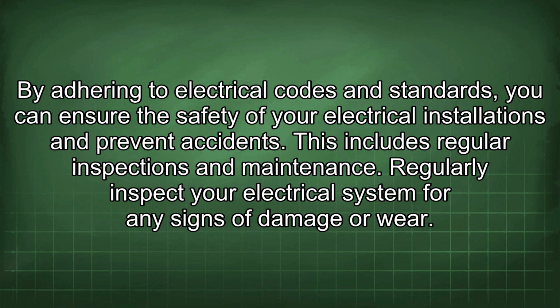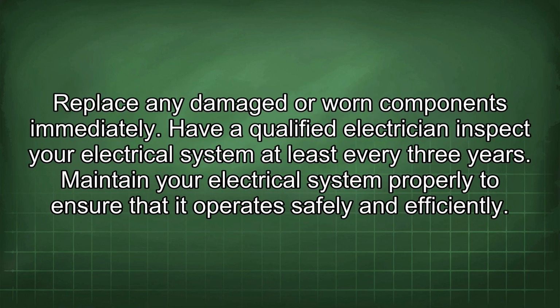This includes regular inspections and maintenance. Regularly inspect your electrical system for any signs of damage or wear. Replace any damaged or worn components immediately. Have a qualified electrician inspect your electrical system at least every 3 years. Maintain your electrical system properly to ensure that it operates safely and efficiently.